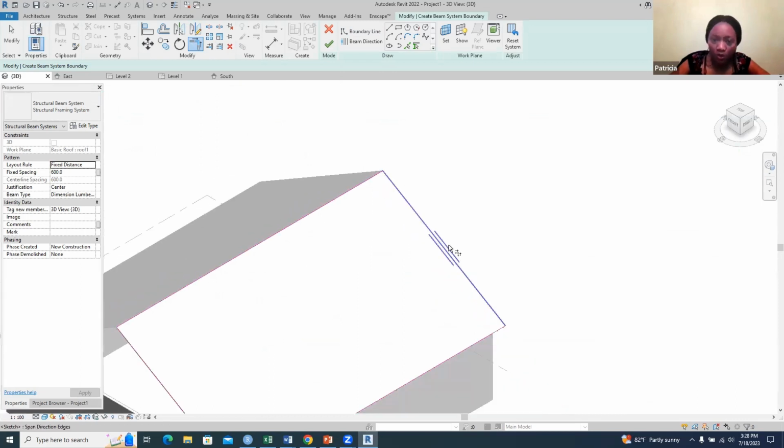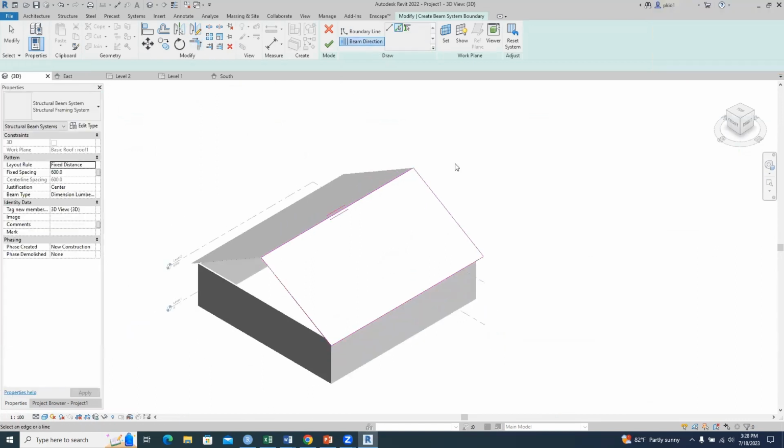And then this one we talked about, so instead of vertical, now we're going the horizontal beam direction. So beam direction, and we select this one. Then we set our spacing. So we'll still go out and change the size to the polygons that we want. If not, we should have created it first, but now we have to select. So let me make the spacing big so that I will not have too many. So I can make the spacing to be 1,200.